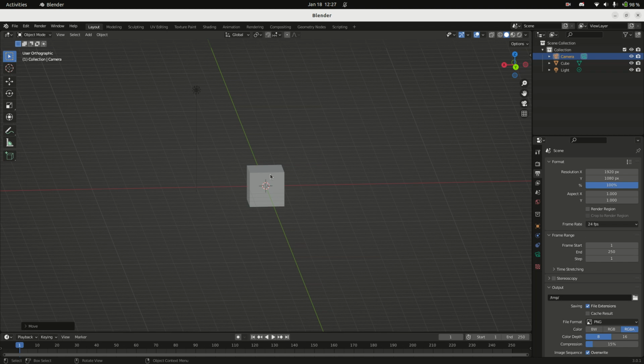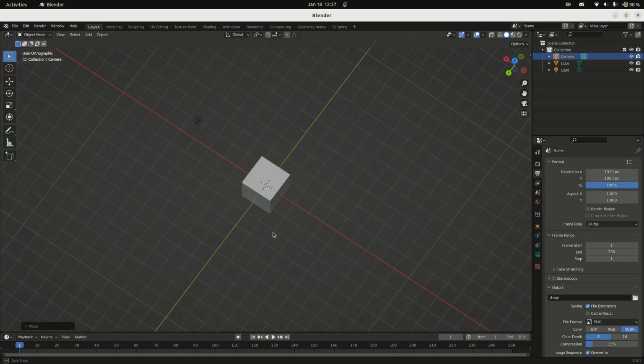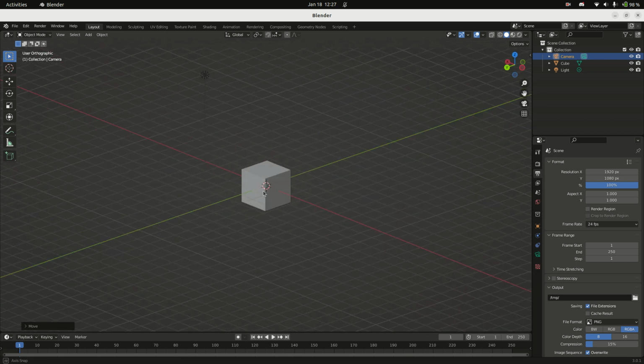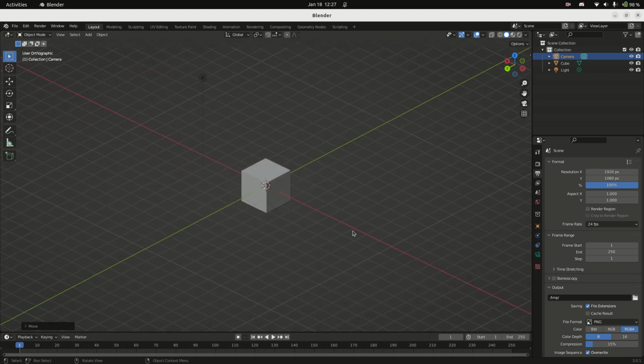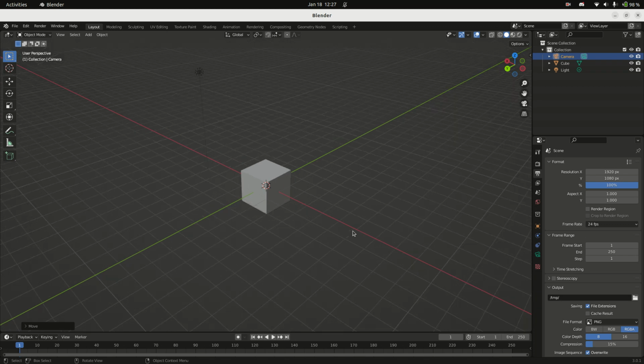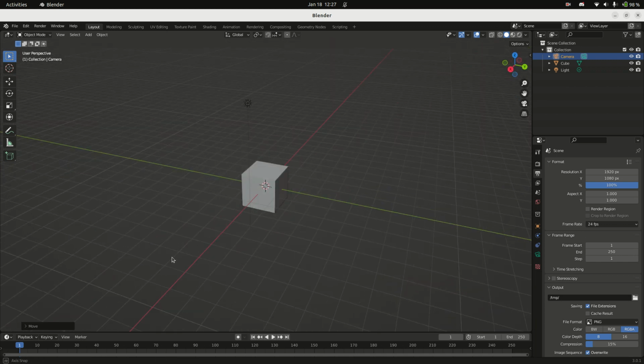But if you ever get in a weird view, and it can be hard to understand what you're looking at sometimes when you're accidentally in orthogonal view, like the default icon for Minecraft, which is a cube drawn in orthogonal view, like that. Number pad 5 puts us back into perspective view, which is what we're more likely to be used to working in. All right, so there are other views to look at too.